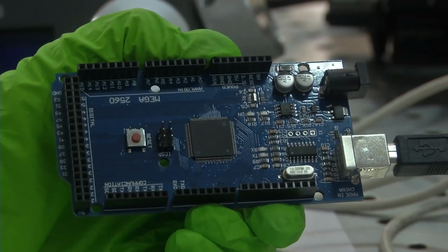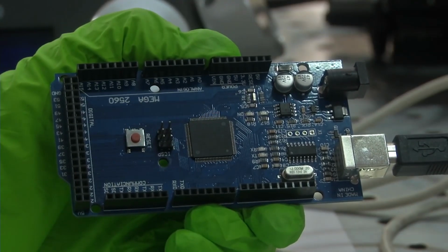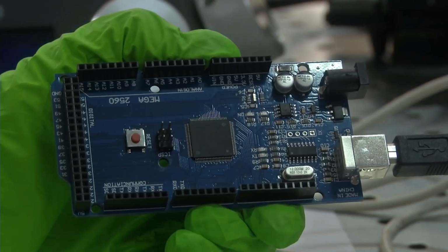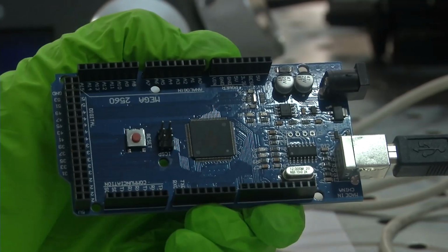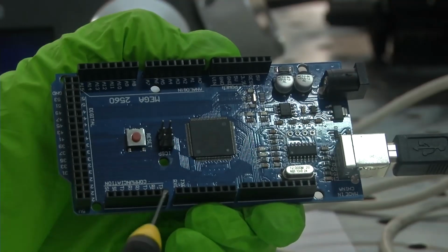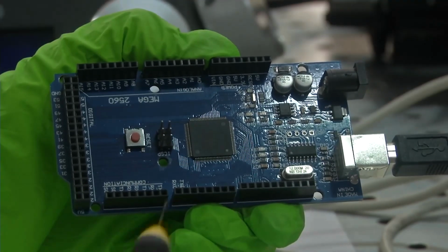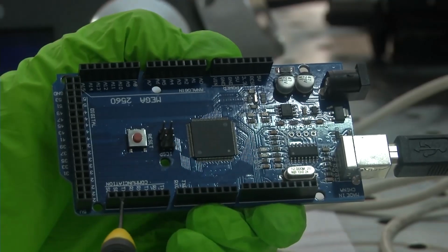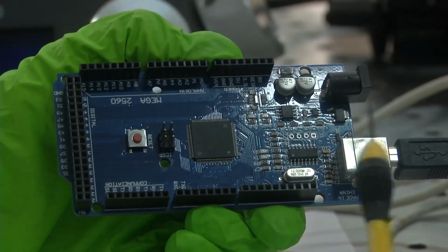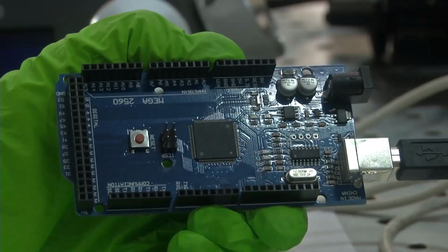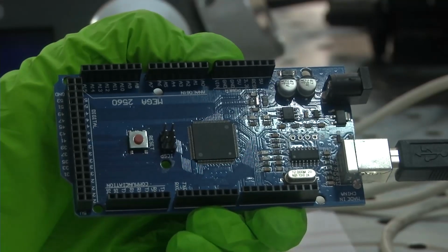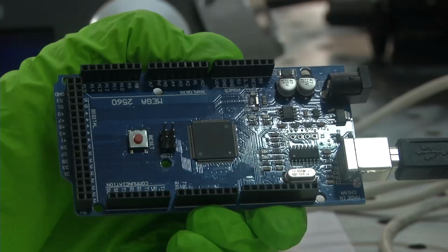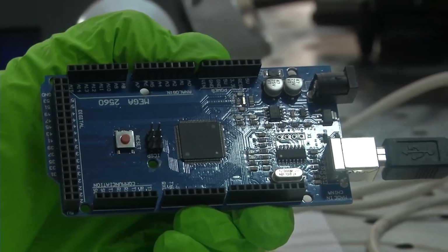It becomes the brain of the Arduino board. Arduino Mega has a major difference compared to Arduino Uno. It has 4 UART ports. For Arduino Uno we can take TX RX from one set only, while we have 4 of them for serial communication. Now you can see a power jack over there in the Mega where we can power it up. You can provide up to 15 volts. It already has a voltage regulator and a current regulator inside it. But a safe operating voltage is 9 to 12 volts, so it's better to keep it that way.